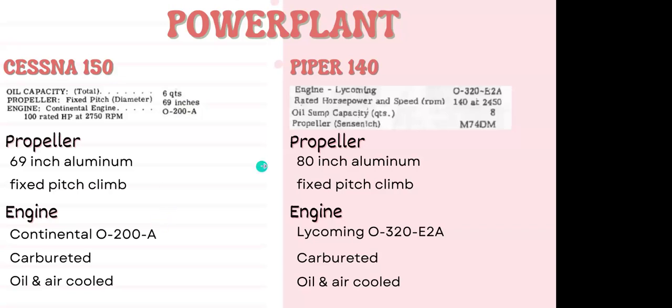Okay, wonderful. So as we talked about a little earlier, since we don't have that I in the beginning with the O, our engine on the 150 is carbureted. And what that means is that we have a carburetor. That means as pilots, we have a little bit more direct control over our fuel air mixture going into the engine. Whereas with an injected engine, it's a little bit more digitized with the way that they program that fuel air mixture. So with the carburetor, as you all know, we've got two knobs in the cockpit.